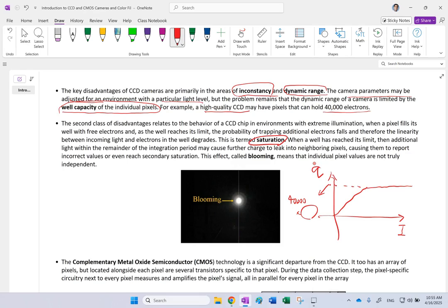So an object that has so much light intensity and another object that has twice as much light intensity could look the same in your image, because the one that is not as bright already saturated the camera, so the second one will definitely saturate the camera. And so above so much light intensity, all the objects might look alike, okay, because your camera is saturated.